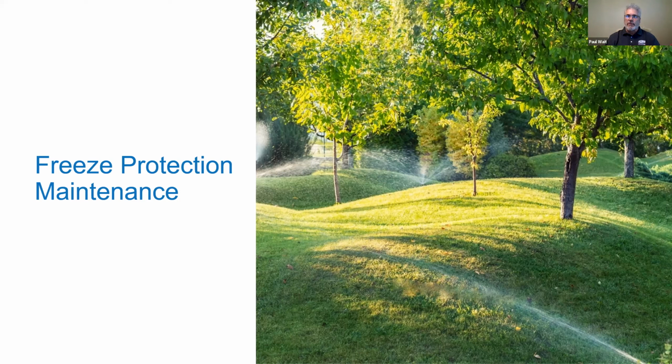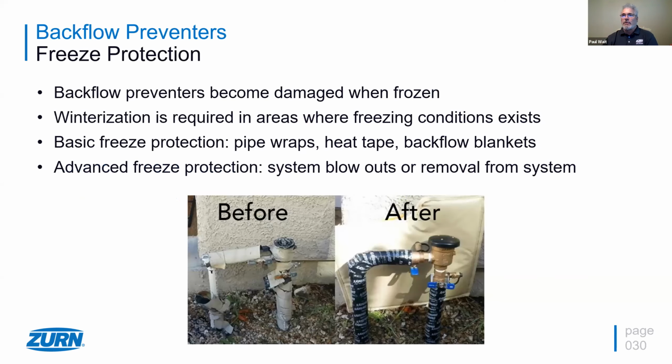So maintenance is really important, and freeze protection is really important in a lot of the areas that get cold weather. One of the things we all talk about during the winter, and some of these winters have been very cold and brutal, specifically lately, is the big freeze event down in Texas, unprecedented. They don't put any protection on backflow preventers down in Houston, because Houston doesn't generally get very cold weather. Thirty degrees is cold for Houston. Well, when they hit the low teens and single digits this last winter, all the PVBs in Houston broke. It was a major wipeout.